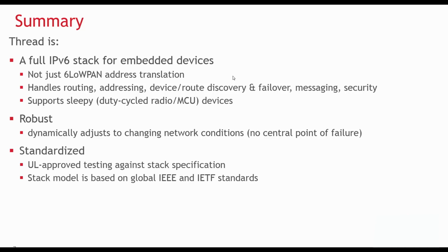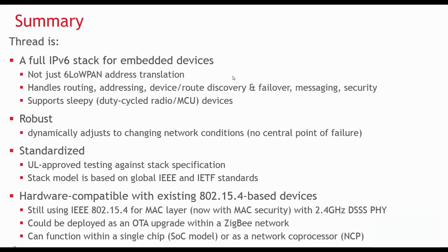It's an entirely standards-based stack model utilizing IEEE and IETF specifications and employing UL approval processes for ensuring stack compatibility with the required set of features. And best of all, Thread is hardware compatible with many 802.15.4-based SoCs and end products already on the market, as its hardware and software resource requirements are similar to that of a ZigBee Pro stack.